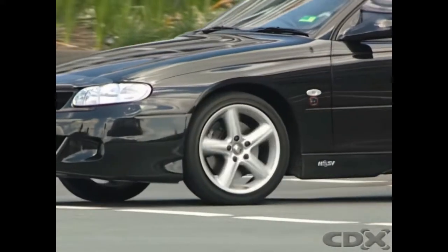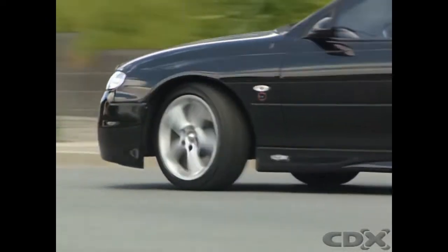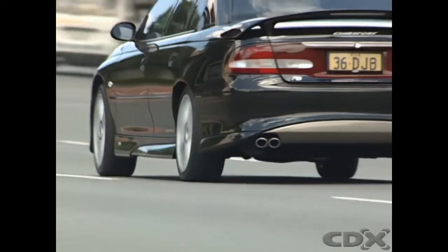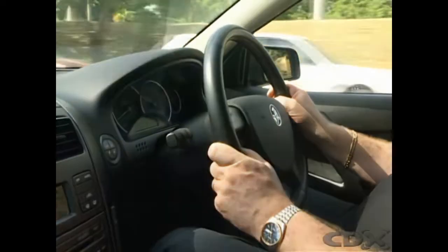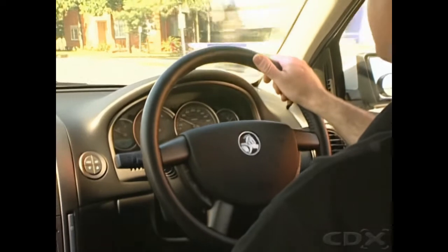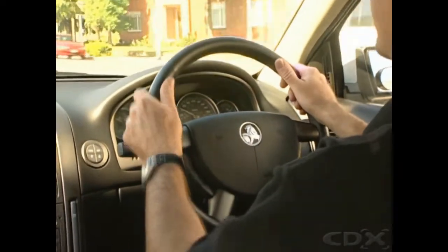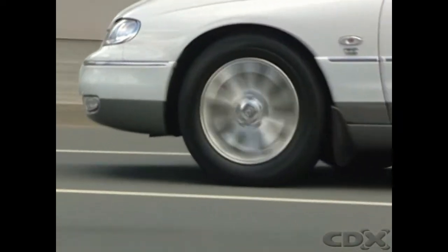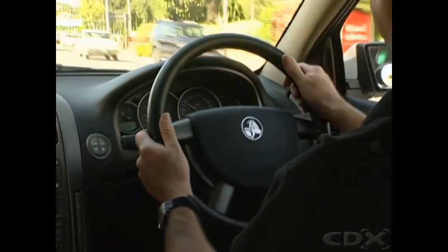With heavier vehicles, increased use of front-wheel drive and wider low-profile tires, more steering effort is needed, so power assistance is commonly used. A hydraulic pump is driven from the engine to provide pressure to help the driver. The power steering system is designed so that even if the engine or the power steering system fails, the vehicle can still be controlled. However, much more driver effort is required.